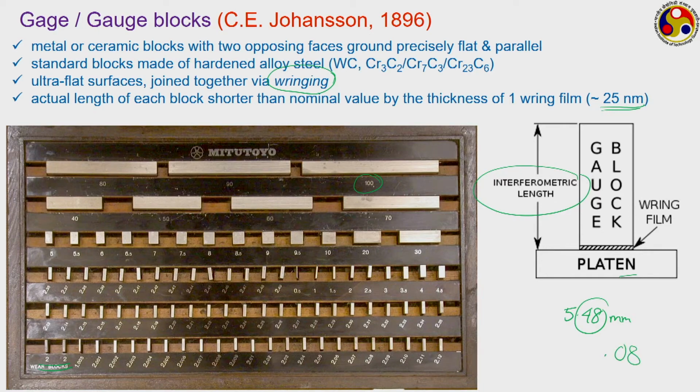0.08 millimeter has to be the smallest possible value that we can use, but there is no 0.08 millimeter block, actually we are starting only from 2 millimeter. So, let us try to identify something which has 0.08 millimeter as the last digit. We are lucky here that 2.48 is there. So, let us take 2.48. Then what else can we go for? We can take a 2 millimeter and another 1 millimeter. So, 2.48, then 2.00 and 1.00, these three together will give you 5.48 millimeter.